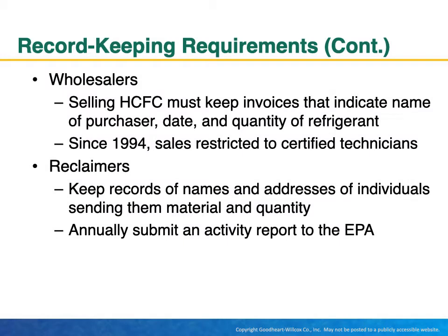Record keeping requirements. Wholesalers selling HCFCs must keep invoices that indicate name of purchaser, date, and quantity of refrigerant. Since 1994, sales restricted to certified technicians. Reclaimers keep records of names, addresses of individuals sending them material and quantity. Annually submit an activity report to the EPA.